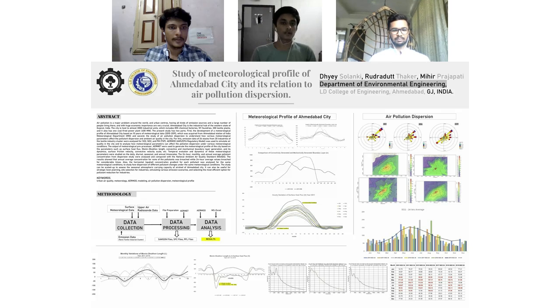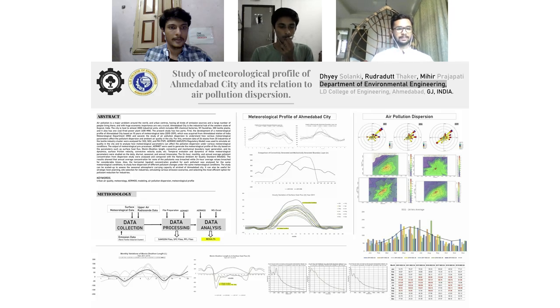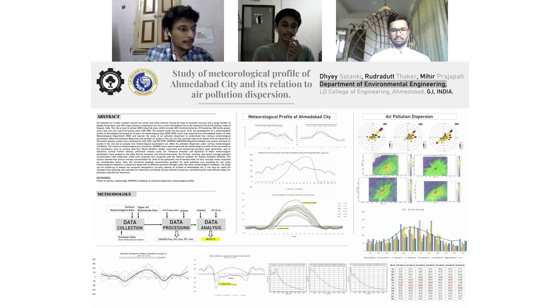Hello everyone. The first two graphs, as you see below, are the Monin-Obukhov length and surface heat flux. In the early morning and the noon hour, the value of the Monin-Obukhov length decreases and the surface heat flux increases. So both are good for atmospheric pollutant dispersion.